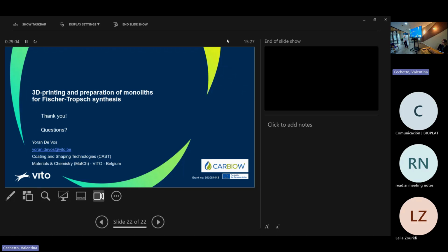Yeah. So essentially, what we typically try to do for catalysis, as we did with alumina, is develop a binder that becomes a catalyst in itself. So what we did with this alumina is we used a boehmite binder. And this boehmite forms gamma alumina when calcined. So you essentially have a pure gamma alumina structure.